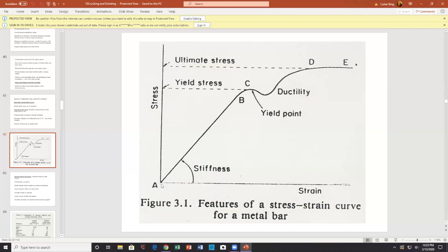Okay. This stiffness curve is also a function of temperature as well. At, say, room temperature it is this curve. However, for plastics, it may be a very shallow curve here. So if I take a plastic and cool it down significantly, I move the stiffness up where it's vertical. So plastic at room temperature may be down here. And when I change the stiffness on it by changing, quote, the conditions of the operation,